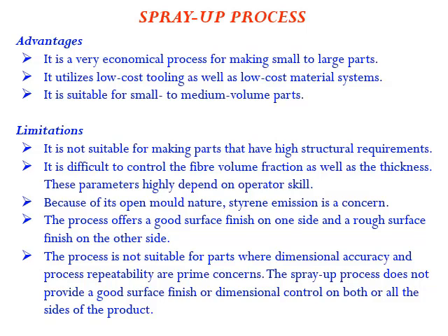So the next one will be the filament winding process. Filament winding is an example of a method in the processing of a composite material, where we are going to have continuous fibers. As we saw in the spray layup, we can go with continuous or discontinuous fibers, but the spray-up process uses discontinuous fiber. This is a process where we go with a continuous fiber.